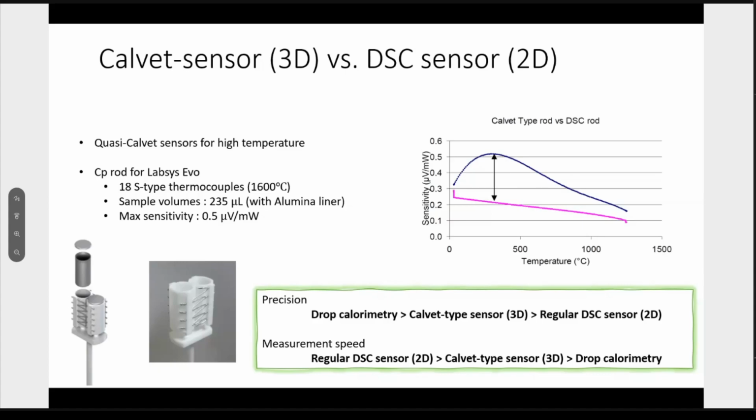If we measure the sample, reference, and the bulk samples, it takes 2 weeks for each sample. In contrast, classical DSC measurement is very fast. It takes only a few hours, but the measurement errors, most of which come from the thermal gradient, are really difficult to control.